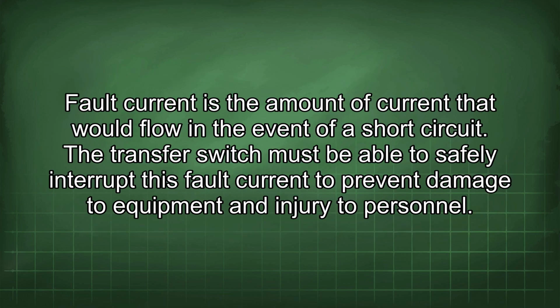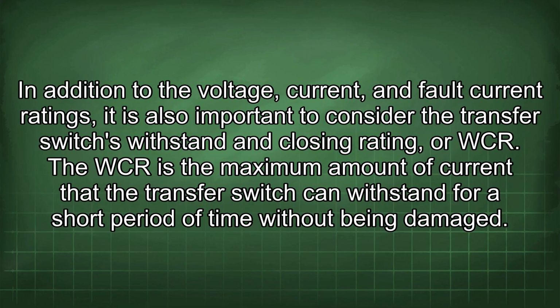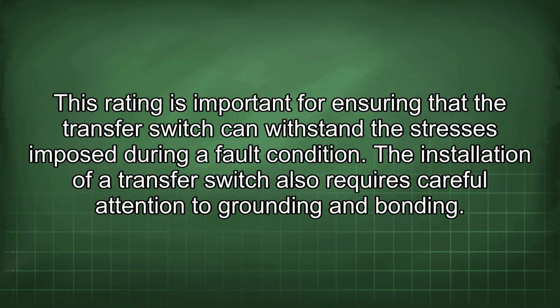Fault current is the amount of current that would flow in the event of a short circuit. The transfer switch must be able to safely interrupt this fault current to prevent damage to equipment and injury to personnel. In addition to the voltage, current, and fault current ratings, it is also important to consider the transfer switch's withstand and closing rating, or WCR. The WCR is the maximum amount of current that the transfer switch can withstand for a short period of time without being damaged.